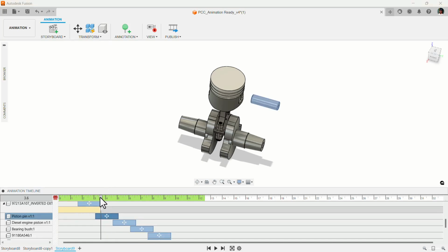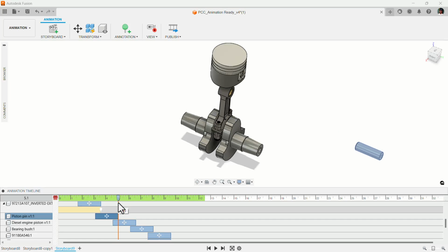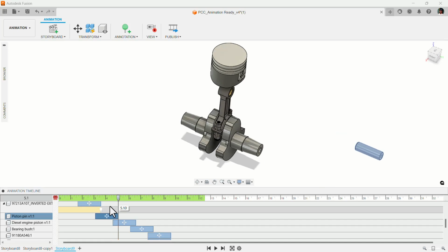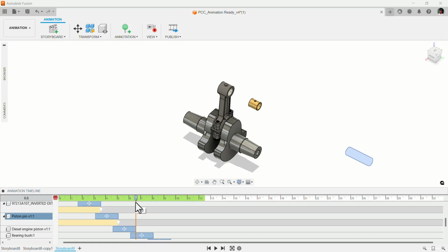I'm selecting this component and place your cursor carefully. If you place your cursor here and if you select the show or hide, that feature will be reported at that point. So that's why you just carefully put your point and capture the hide or show. You can move this action also. You can even delete it, right click and delete it. So all these options are available to you.